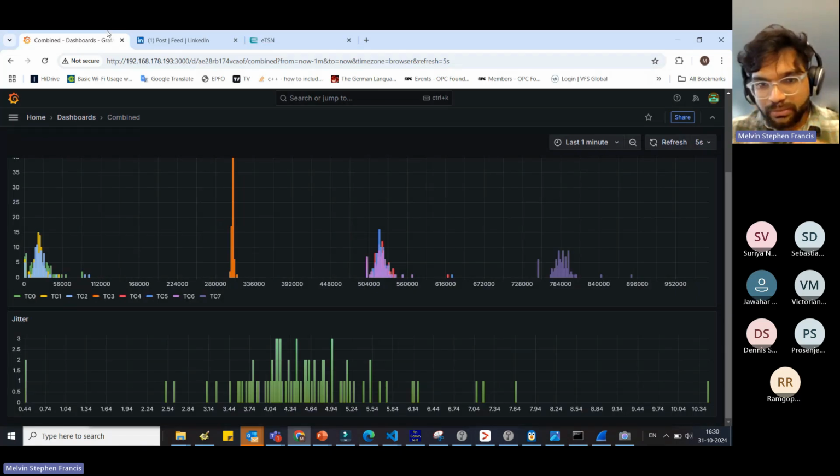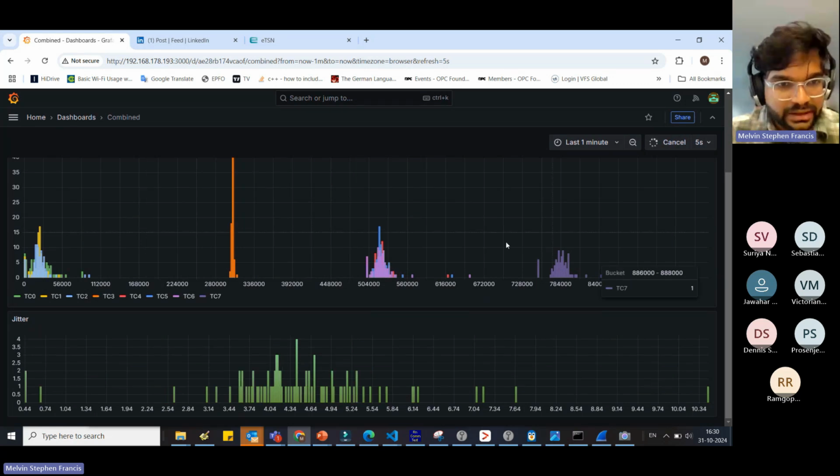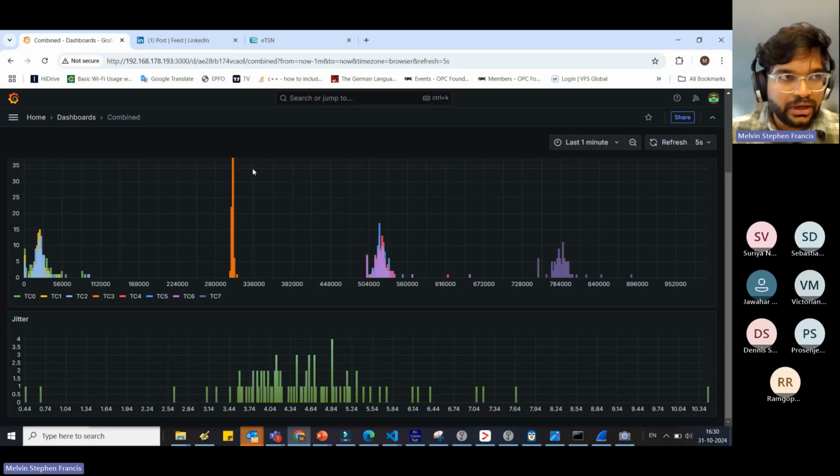Quickly, I want to touch one point. This round robin system is working at 1 millisecond now, and we can also go down to 100 microseconds. This is a 1 Gbps network, and it can also be scaled to 10 Gbps. So hardly will your packet need to wait even 1 microsecond for real time purposes.